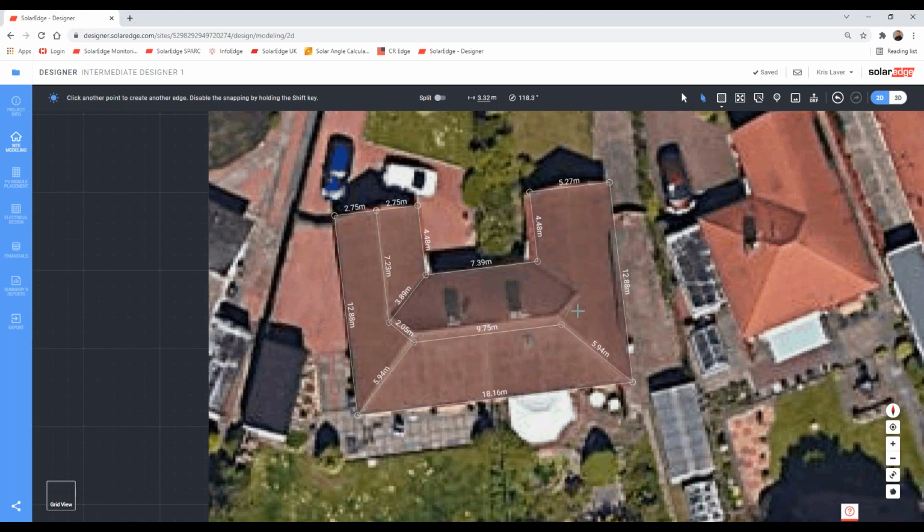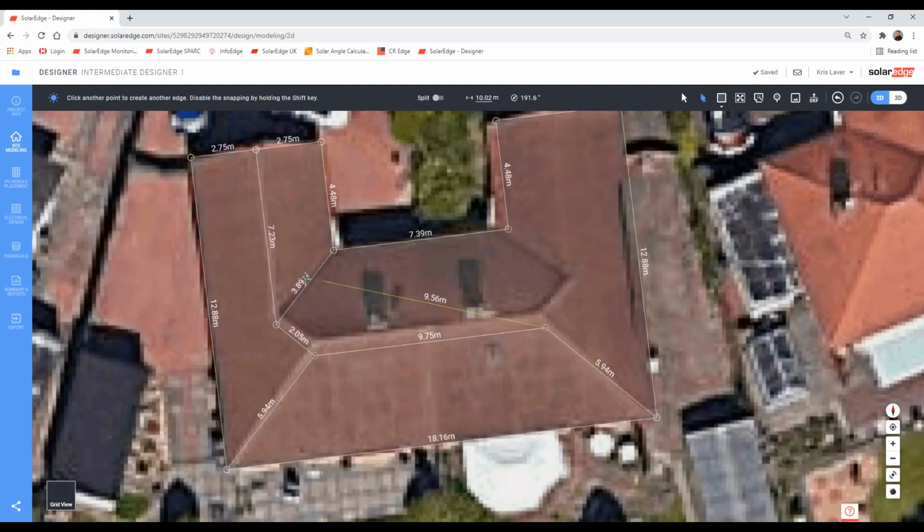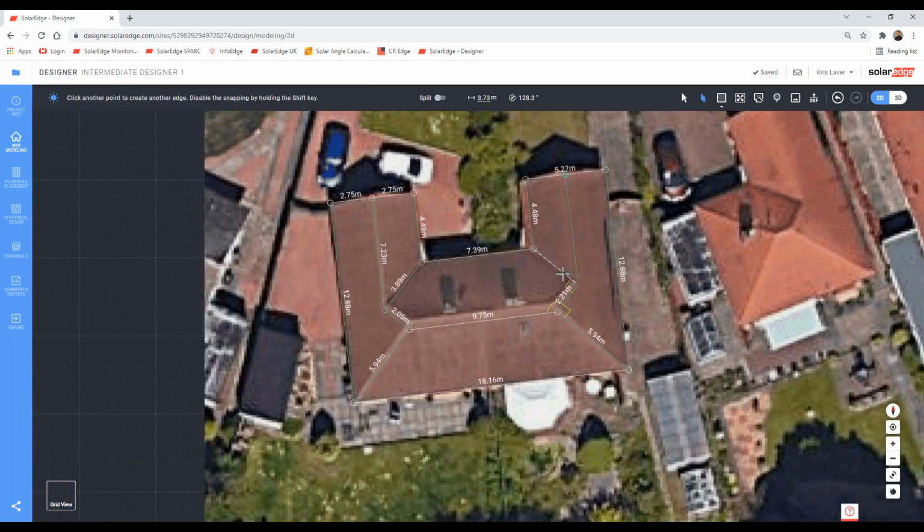So when this line goes dark green, which is there, it's telling me that I'm parallel with these lines. If I float that up there, it's telling me there I've got the 90-degree angle I want to this section, and I've got the line here to the middle section. Nice bit of indication from the software. So click there, connect that line, simply draw that line through.